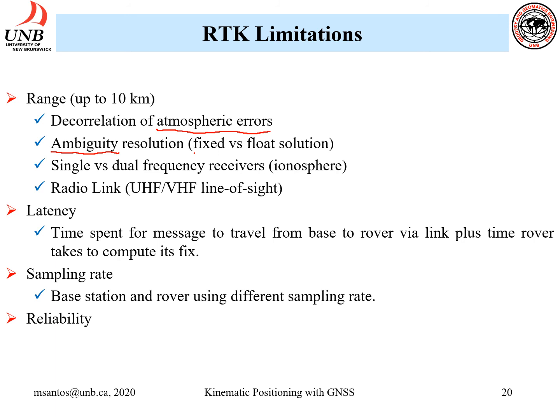So we can either fix it, solve as an integer number, or solve it as a real number. It is more difficult to deal with the ionospheric delay if we deal just with a single frequency. With dual frequency receivers, we can formulate the ionospheric delay free combination.